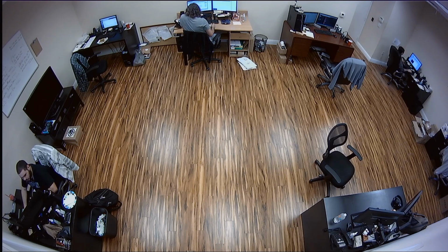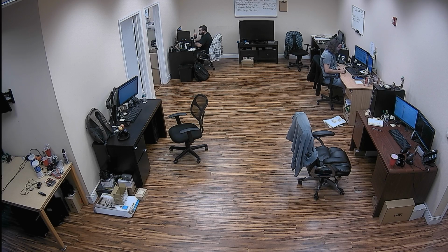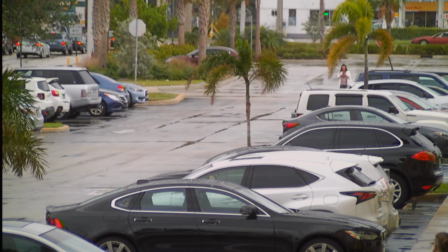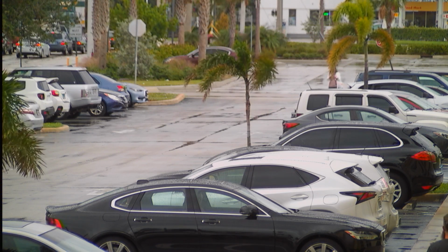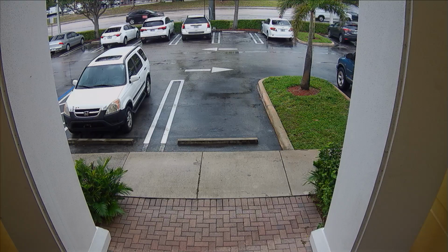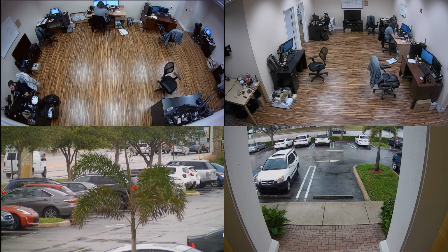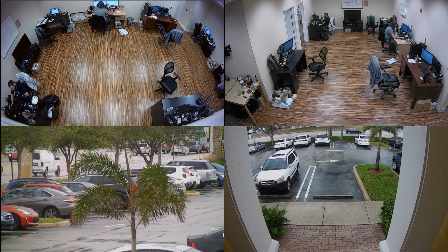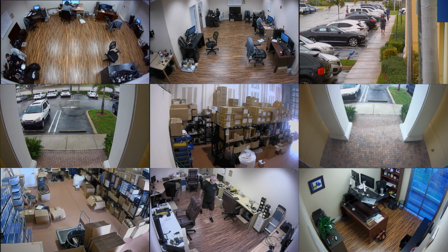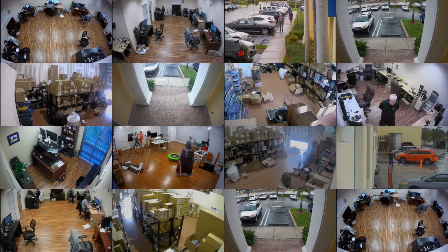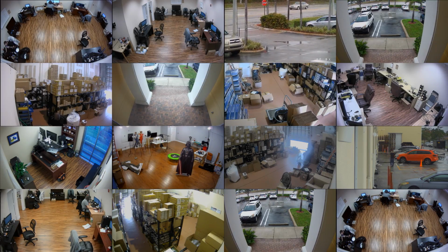And again, the DVR's HDMI output is set to a spot monitor mode, which basically allows the HDMI output to continuously display these different live camera views, and it doesn't impact the operations of the DVR. We have another monitor set up using the VGA output, and that allows us to control the DVR to search through and play back recordings, and that doesn't impact this HDMI output at all. That's what a spot monitor is.